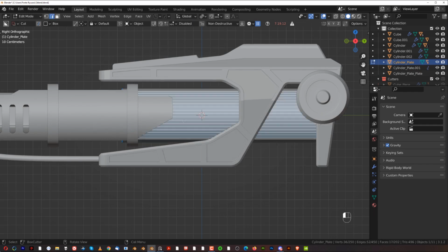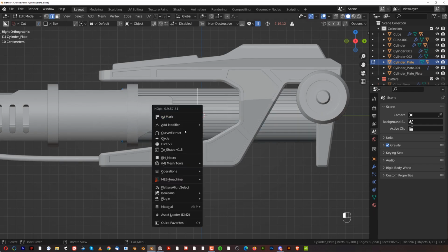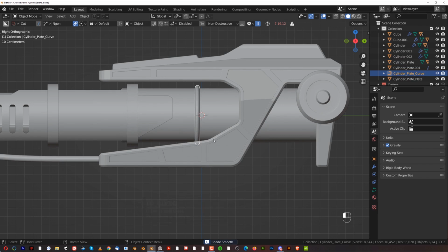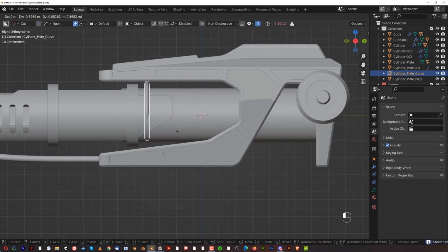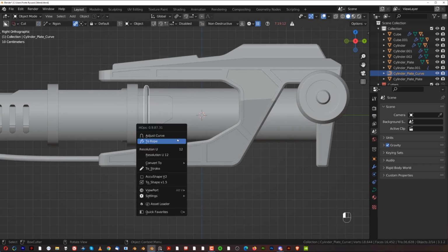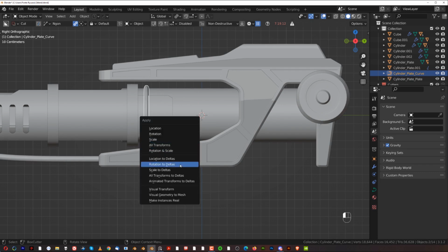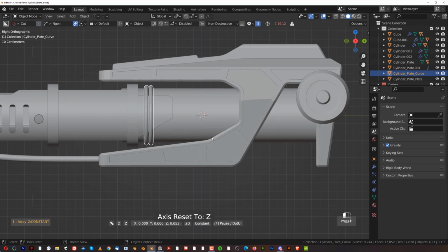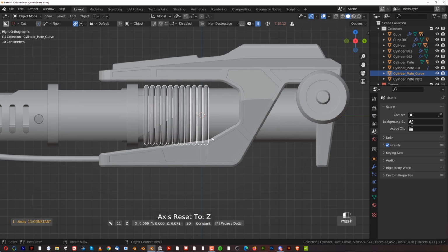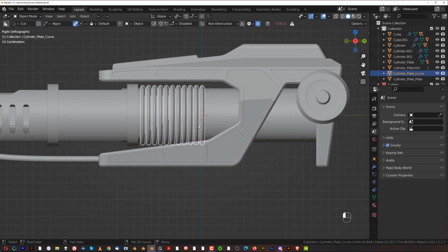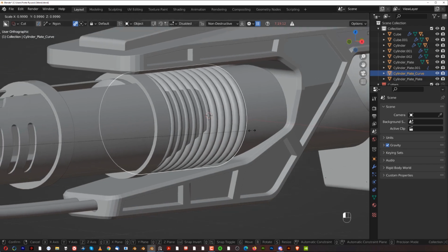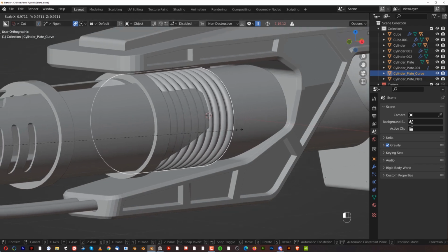So here, for example, what we could do is grab one of these and Shift, curve extract, and press S to scale it, to smooth it, I mean, GG, move it in here, or GY, and then the radius, right? So Shift Control A, visual to mesh, and the radius. And the cool thing about blockouts, guys, is that this doesn't have to be the ultimate version of it.